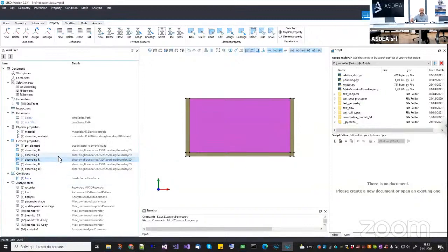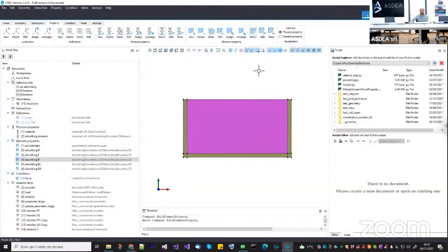So what I decided to do is to create a much easier approach. Okay. So I will show you how to convert this one into the new version. Okay. So the first thing, I'm going into sub-selection, and I will remove all the boundaries because now in the new automation, STKO will automatically extrude the boundaries, okay, while computing the OpenSees solution. So I remove this one.